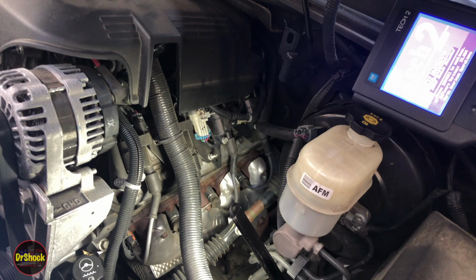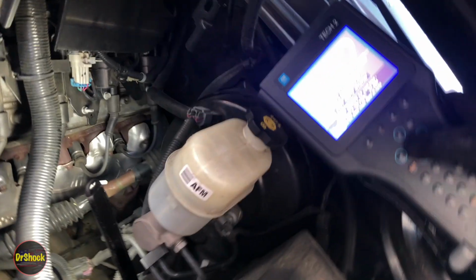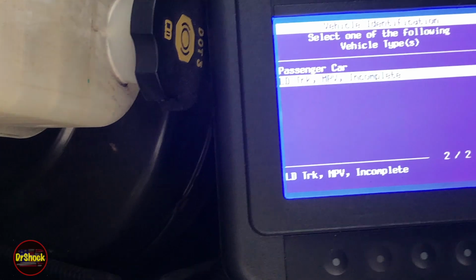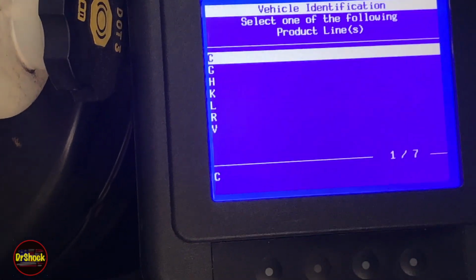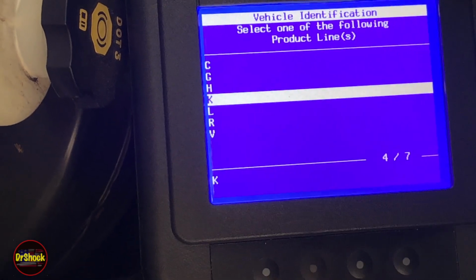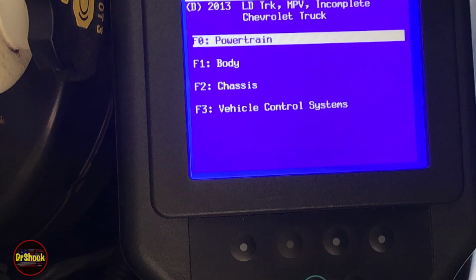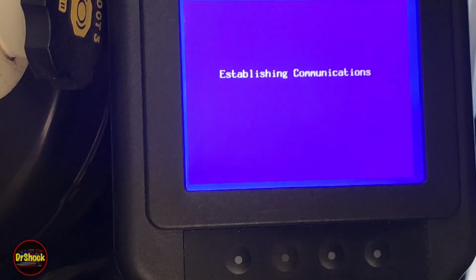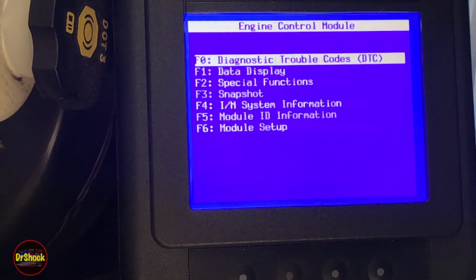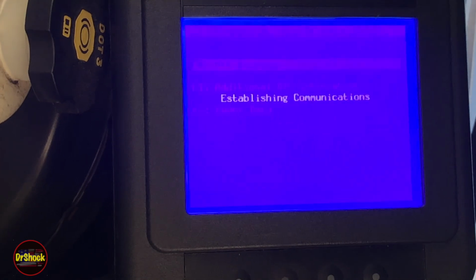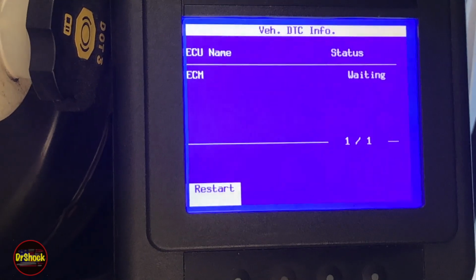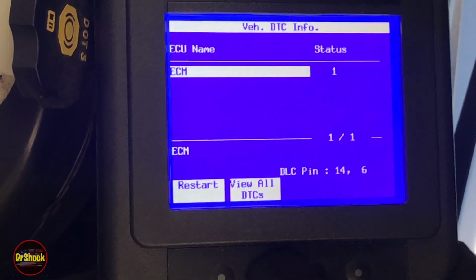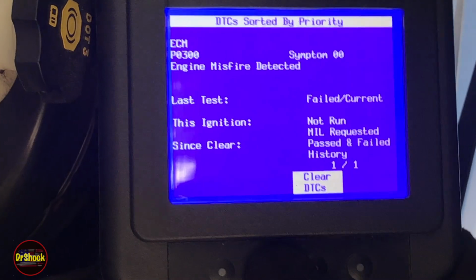All right, so sometimes these will reboot because when you start the engine, you pull the voltage down below the minimum that these guys can stay running. So let's just go rebuild the vehicle again. There's some other kind of noise going on here, but first I want to see, did we get any other different codes? Nope, still the same one code.